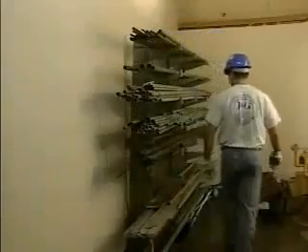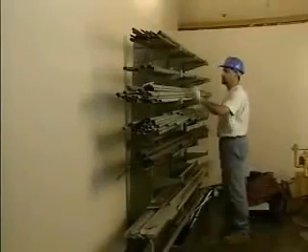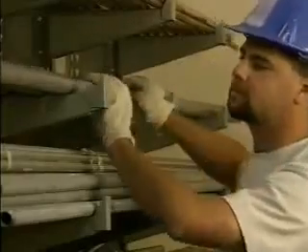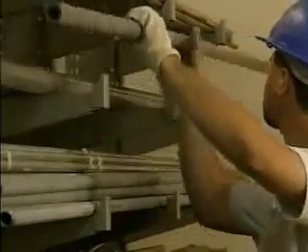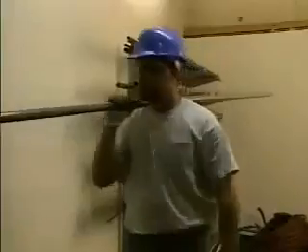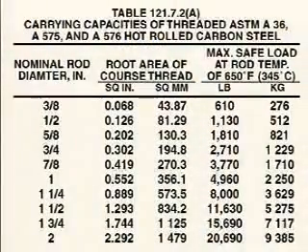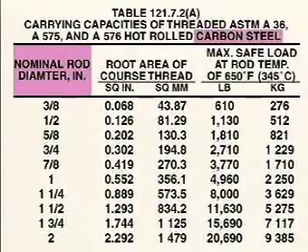Though pressure is generally the concern of piping system designers, it is important for maintenance personnel to understand schedule numbers in order to identify the proper pipe for a specific job. The American National Standards Institute, an organization that publishes guidelines about pipe materials, sizes, and applications commonly used in many industrial facilities, has developed working pressure ratings for different types and sizes of pipe. The working pressure rating lets piping system designers, as well as maintenance personnel, know the amount of pressure a specific size and type of pipe can support.